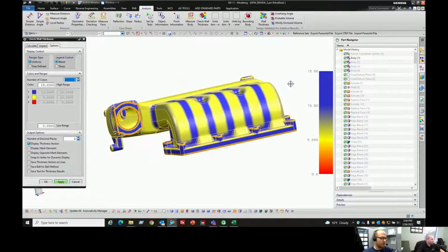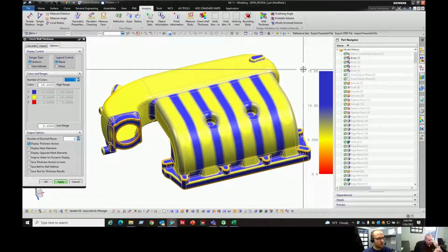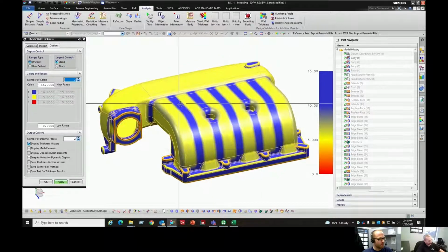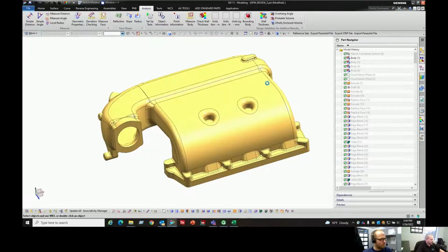Okay, so this process, you're trying to maintain the general interface of the original casting, but you're also worried about the function of the mold and the solidification of the casting. It doesn't do me any good to just make a mold of this specific casting, because you're going to end up with some shrinkage in these areas if we can't feed them. So that being said, that's the basics around the DFM for those couple ones.